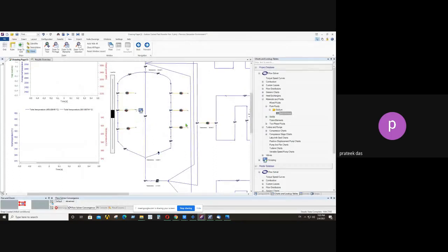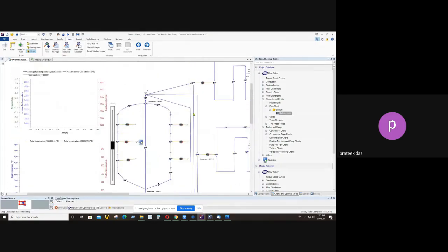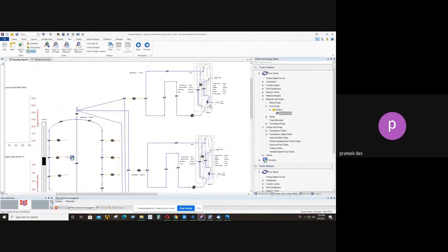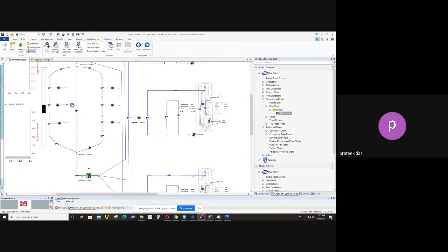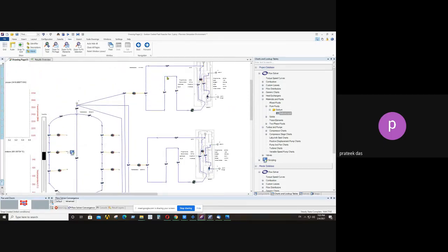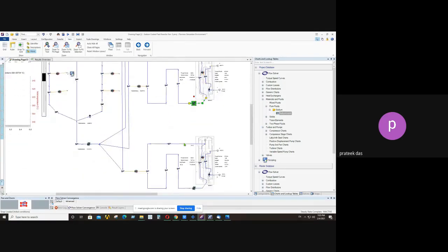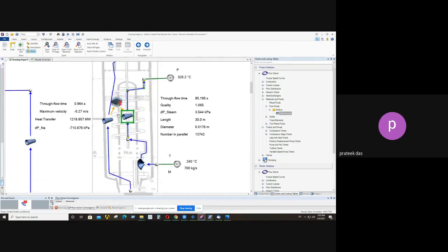It is the primary loop and it is the secondary sodium loop, and this exchanges heat with this water loop. So you can see for this primary loop circulation, one sodium pump is there, and for secondary sodium loop circulation, secondary sodium pumps are there. These maintain the flow of the secondary sodium loop, and it is the steam generator in which the water is exchanging heat.